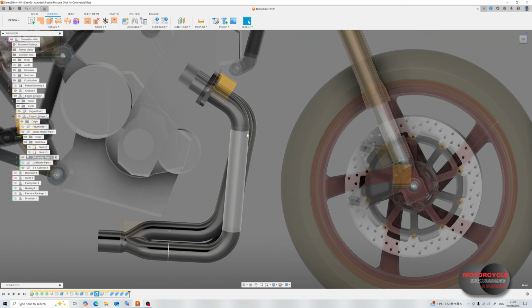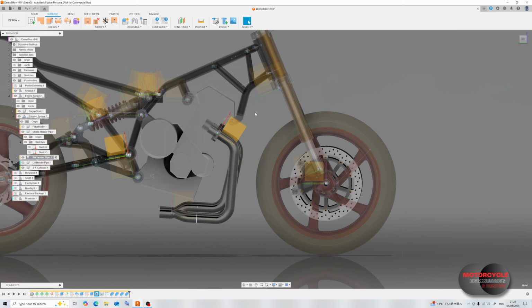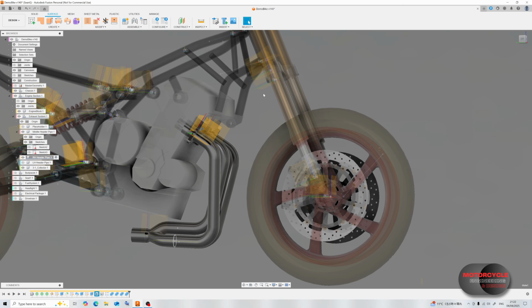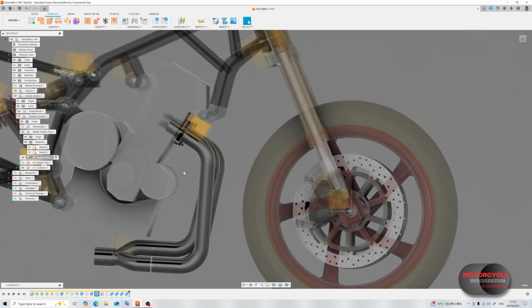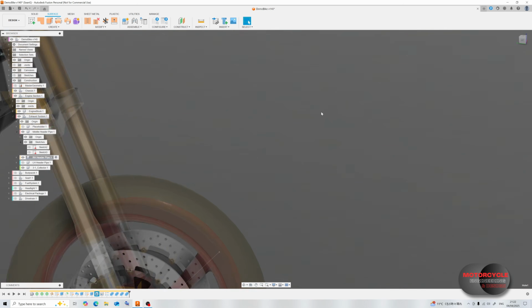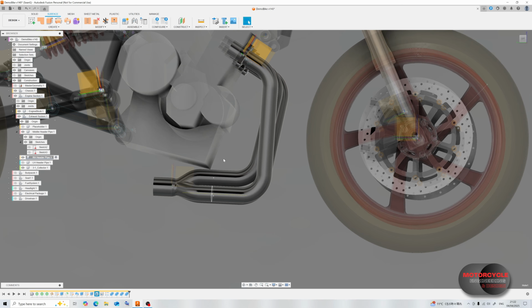Some things to bear in mind. If you have a real model for your engine, or what you're modeling here, if you have a real reference, then you can check everything in regards to packaging. I can see very clearly that I have no space for a radiator in this case. As soon as you have any travel in that front wheel, we're destroying the radiator. This definitely needs to be pulled in, and then the pipes need to probably be pulled out and do some more twisty geometry.